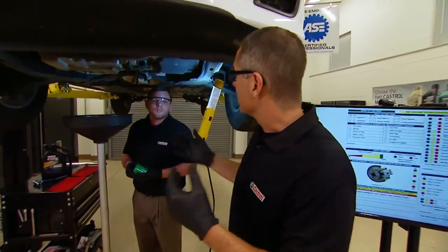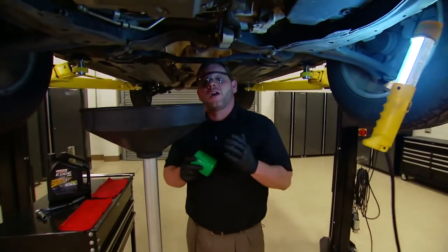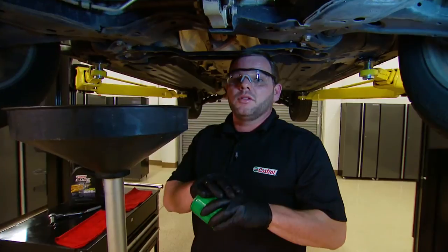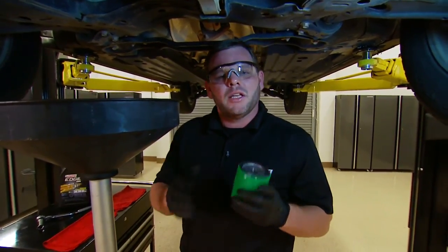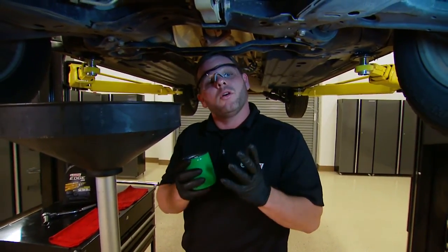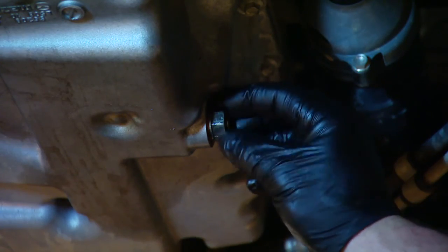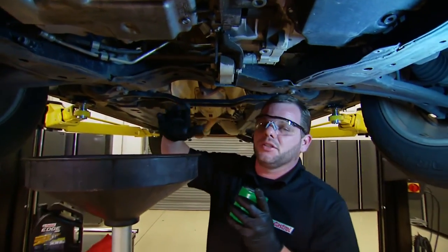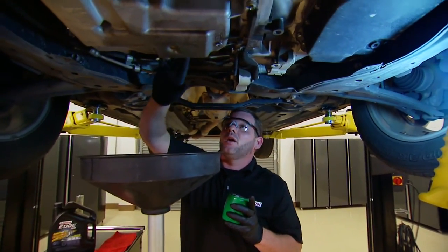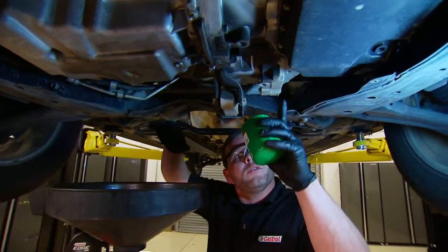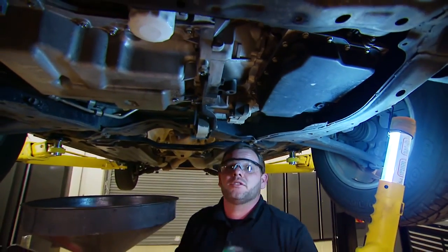Chase, what can you share with our viewers here? Well, to perform an oil change, this is how I like to do it. The first thing I like to do is make sure I got my safety glasses on and my gloves. And then I want to crank the engine up, let it run for a few minutes so the oil will warm up and then drain better. Now I'll come over to my drain plug. I want to remove my drain plug, make sure my gasket's in good shape. Then I'll go ahead and look at the rest of my undercarriage here. I want to look at my oil pan, make sure there's no leakage there. Maybe look at my transmission, just make sure everything's in good shape.